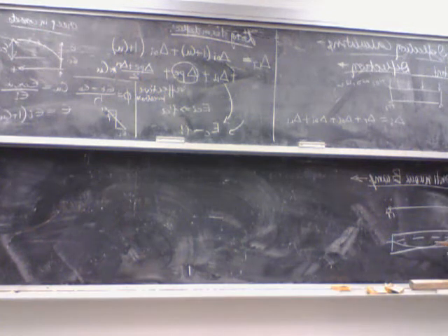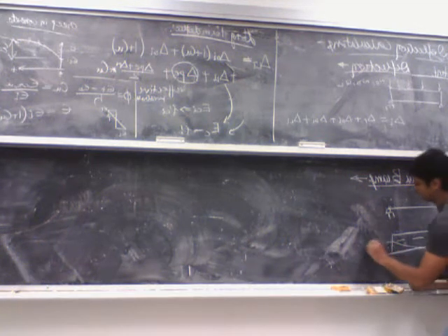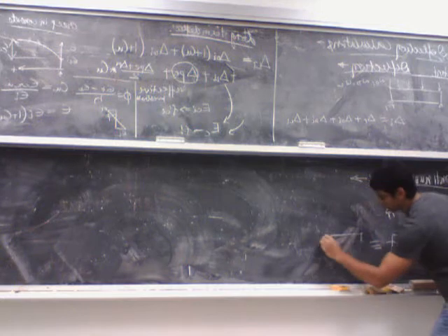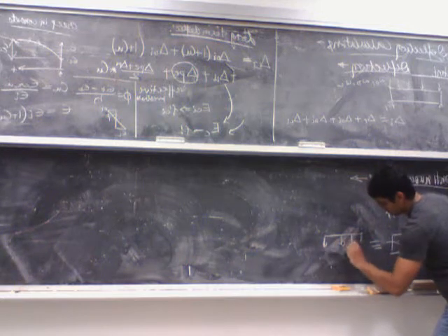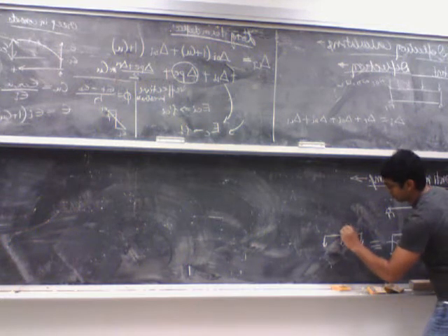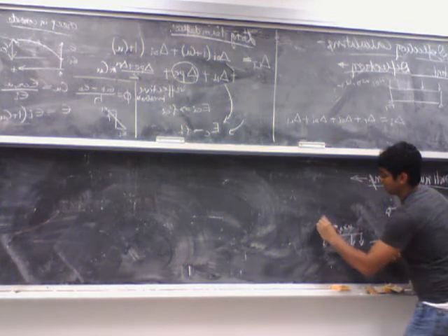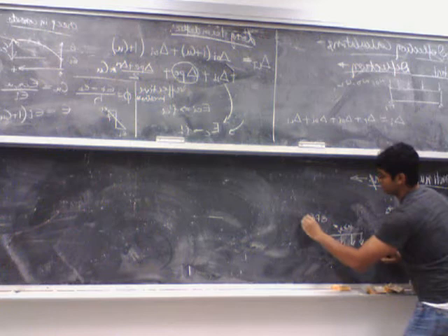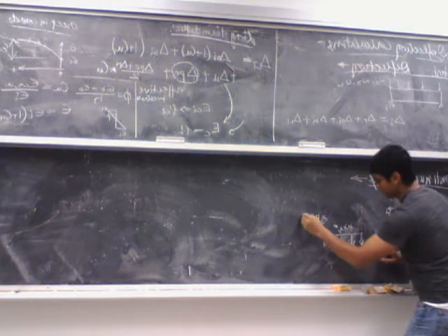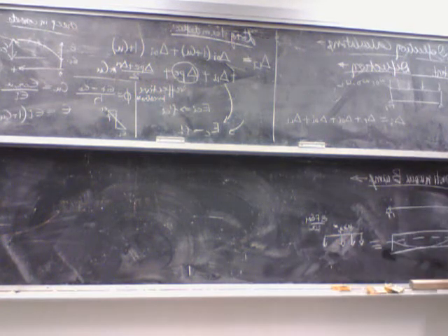In this case, we know that this parabola will create an equivalent load, similar to a distributed load, W equivalent, which is given by 8F delta M over L squared. I'll define what delta M is.